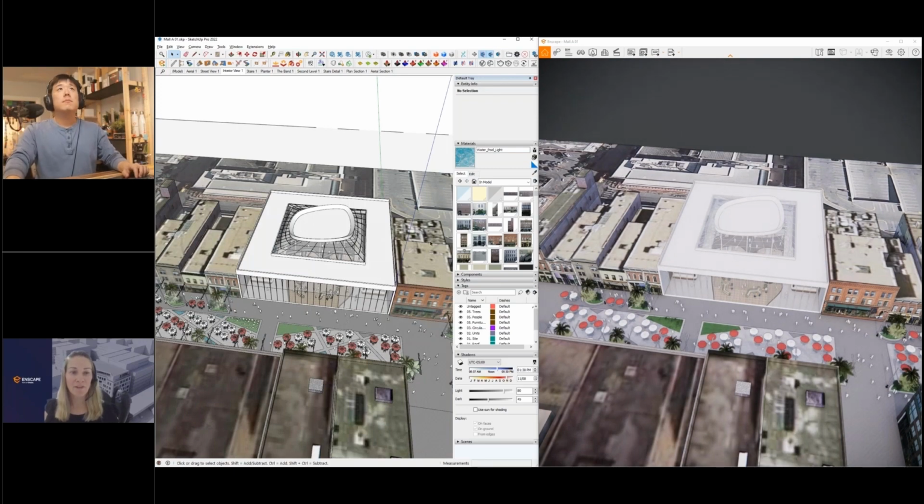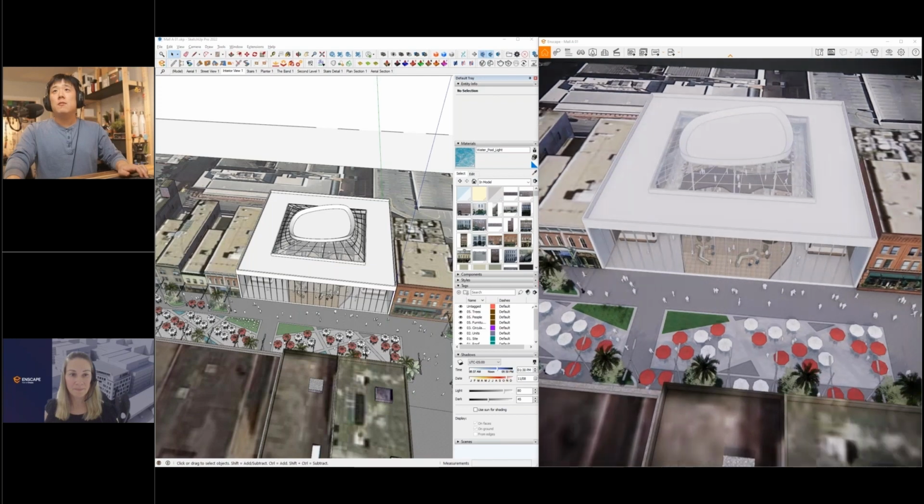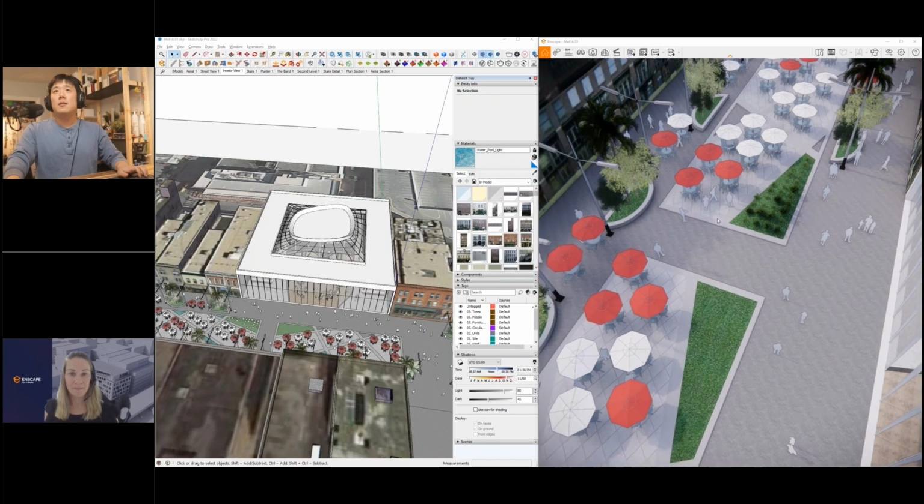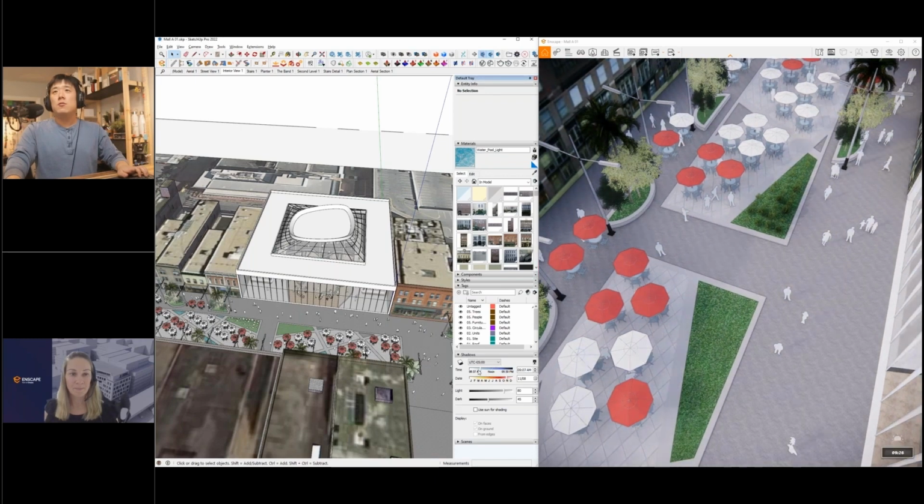Can you save the sun direction in Enscape? Oh, well, I would actually rely on SketchUp's sun direction because it has an excellent shadow tool. I dare not turn it on ever in front of a client or your coworker, because if I turn that on right now, my machine's just going to come to a halt. Whereas Enscape actually interprets that data and shows it correctly to you. Whilst I have minimized the shadow line, you can see it here. If I were to change that, you see how that starts to change. So that's how I would manage.